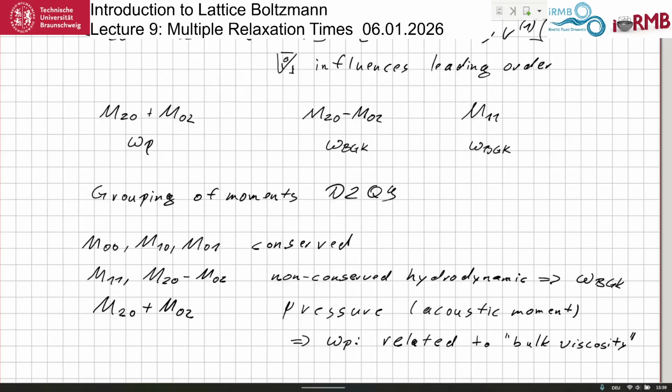And this is due to bulk viscosity being higher if there are particles in the air. So usually you don't have a good feeling what this should be. Don't believe anybody who is telling you that the bulk viscosity should be the same as the shear viscosity. That's not true. It's just difficult to specify what would be correct.